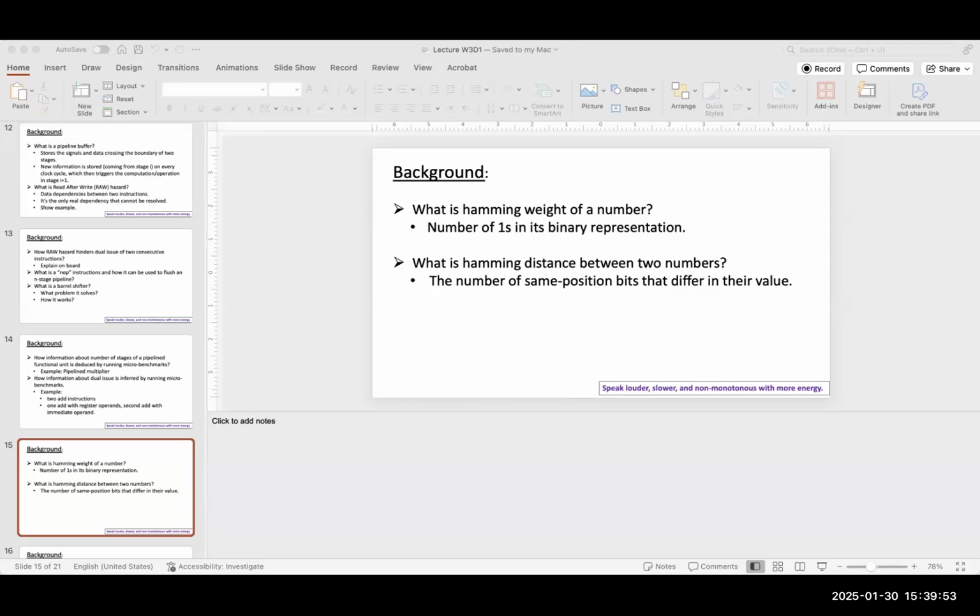Any other question? In conclusion, there are only two ALUs, one for the registers and the other one that functions with immediate numbers. No, we are not saying that. What this table is telling us is that we can have one ALU instruction with an immediate operand dual issue with another ALU instruction which doesn't have the immediate operand. But it doesn't say that one of those ALUs can only perform the plain ALU instruction and the other can perform only the ALU instruction with an immediate number. Both of them can do both; it doesn't tell us about that.